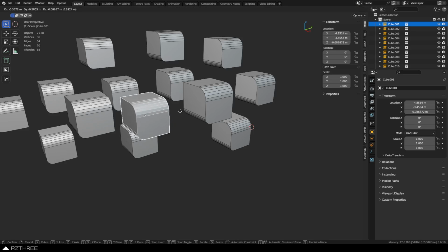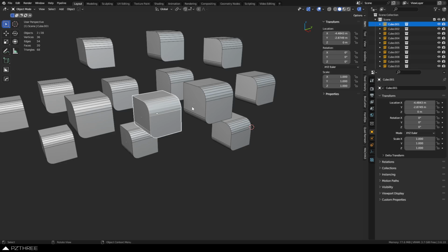So this is going to be one of your best ways of saving performance. Now, anything you can recycle though, any kind of texture, I'm talking about just the individual texture, not even a material, if you can recycle those things over and over and over again, you're going to save memory. And that's really what you should be doing, thinking about using as many things that will create an instance-like behavior, such as mirror modifiers or arrays, but also doing this here with the actual placement of things using collection instances.